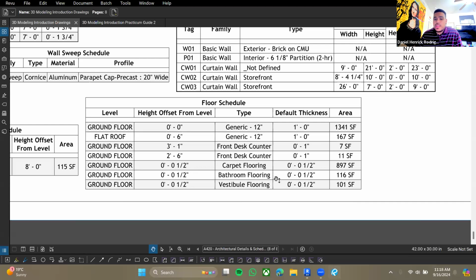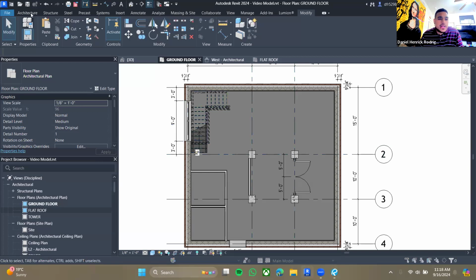And they also have a thickness. So these are all half inch and they're half inch above because the floor slab has a height, and that's on the ground level height, and then you put down another floor on top of it. It's going to try to be on the same level. It's going to clip through and be the same. So I just set a little half inch offset there, and you guys are going to have to do that.